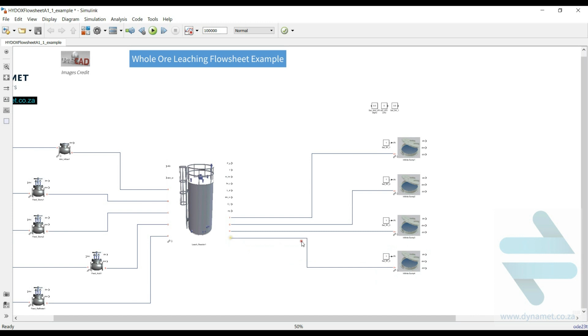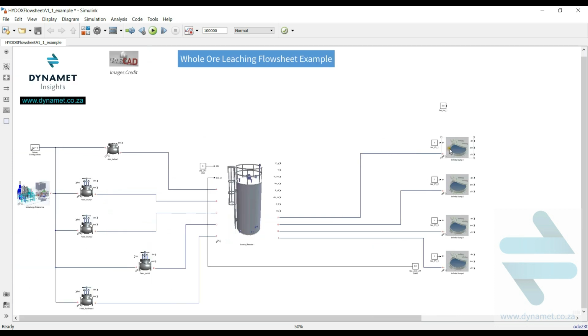Finally, the sampling and spillage line is also connected to a sump block. Here we could impose any upset on the circuit we like, for example to simulate major spillages on the circuit performance. For now, let's keep this flow 0. Now there's no external heat transfer in this example, so let's make this heat flow 0 joule per second. So we basically have an adiabatic tank other than for the energy flows via the process pipes.